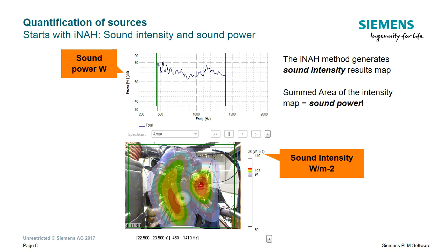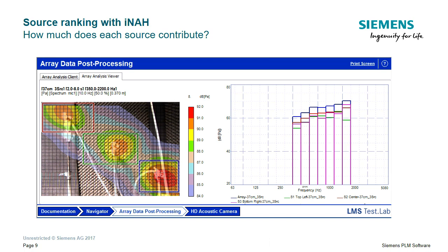If we then draw a rectangle around that hologram, and we multiply the sound intensity with the physical area that is represented by that rectangle, we actually get sound power. So we get, in this case, the sound power of either the entire engine, or we can actually identify different components and we can compare them. So that's something, as we can see in this next slide.